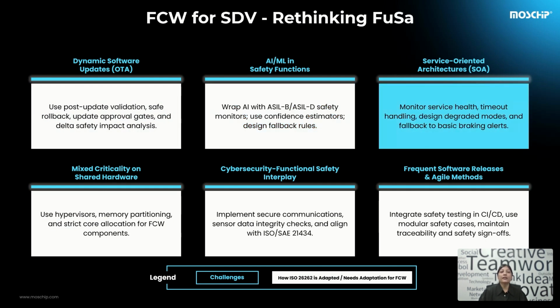Next in the row is service-oriented architectures. Collision logic relies on microservices that might time out or reboot. If a service fails, FCW degrades gracefully to basic brake alerts instead of going dark.